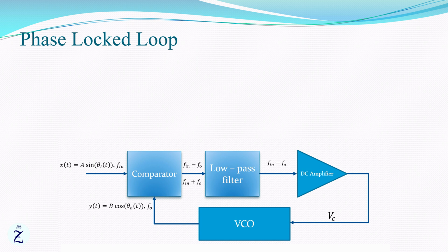Basically, the PLL goes through three stages. First one is free running, in which the circuit produces an output signal having frequency FR. The circuit will be in this stage when no input is applied. So the frequency of the output signal is determined by the external timing capacitor and external resistor.